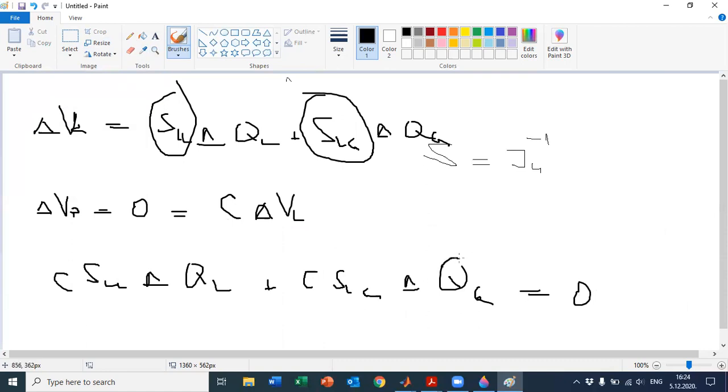So basically, if a disturbance happens, and disturbances always happen in the system in terms of reactive and active power changes in the network, that means that delta QL changes. So we need the change of the reactive power of the generators to completely smooth out these voltage deviations.